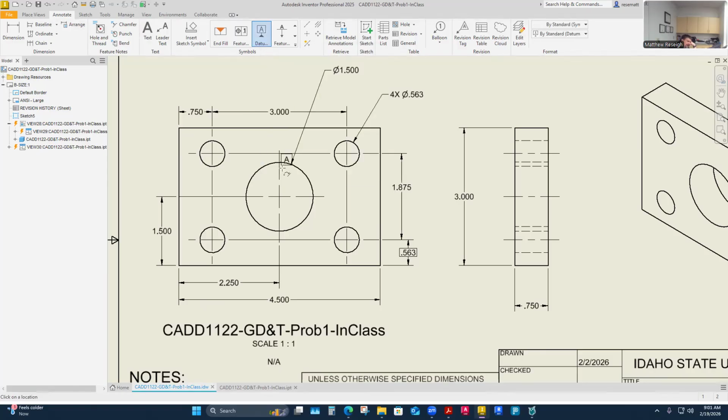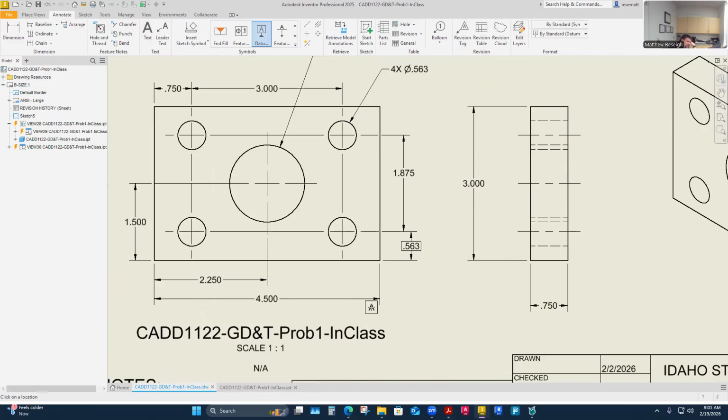So I just select that. My first datum in this is going to be a surface. So surface datums have to be established correctly. There are certain ways you can do that, and that is given on your page. We talked about this even last week a little bit. I flew over this page. I told you I was going to get in the weeds just a little bit, but I'm trying to stay high level weeds. Medium cuts. I don't want to go too deep. I just want to do a couple things.